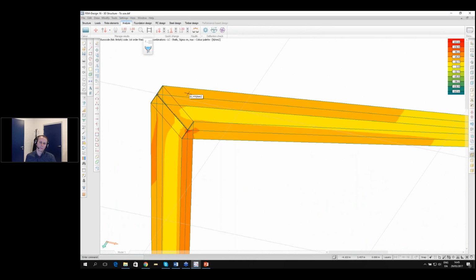If you want to add a splice connection to the frame, I would just model the splice and make a line-line connection to the frame if it was me. But you can also extract the forces on the specific location. You can make the section result and see all your stresses along the whole cross section. But the easiest way is to just make an edge connection there. That is the easiest way. Then you can also send it to Excel.